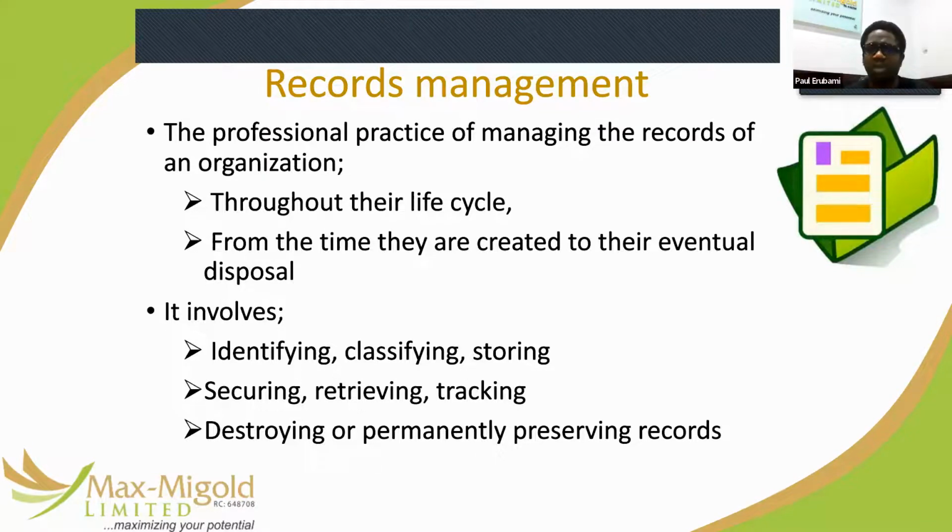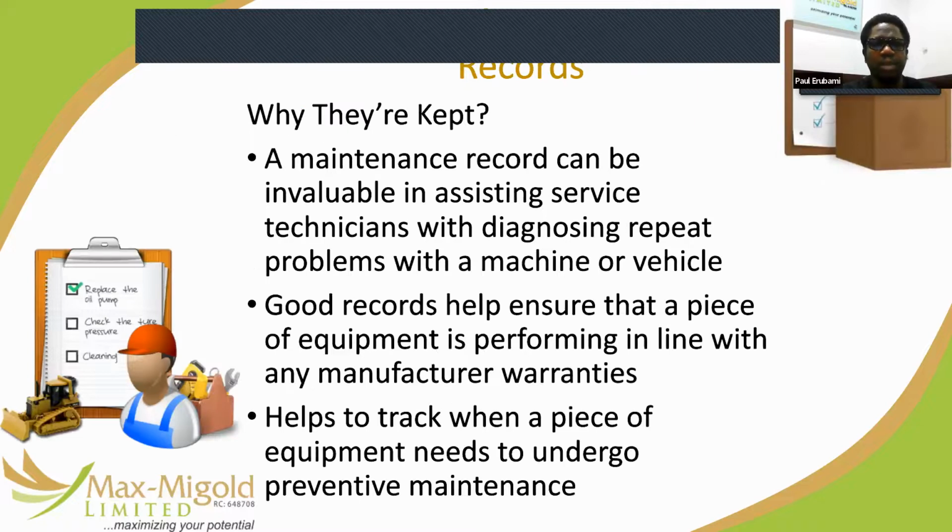If you have a chiller system that will be here for 25 years, you cannot lose information on how many times the compressors have been replaced, and you cannot lose how many times it has failed. That reporting that is extracted from the work order must be kept perpetually on site or in a retrieval system so that people can get access to it.